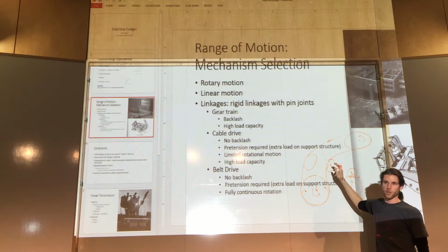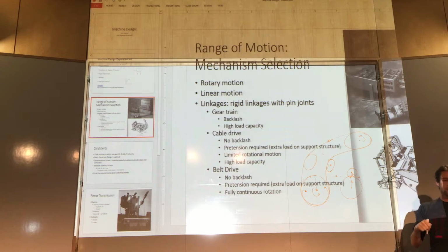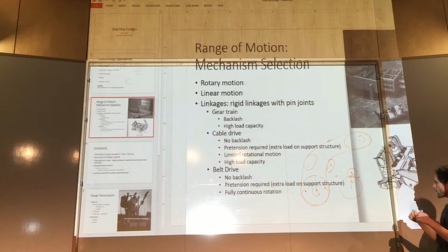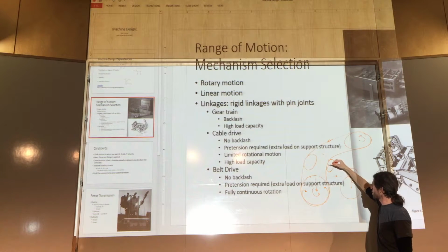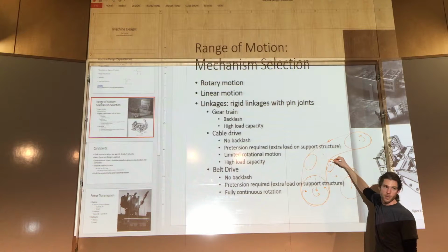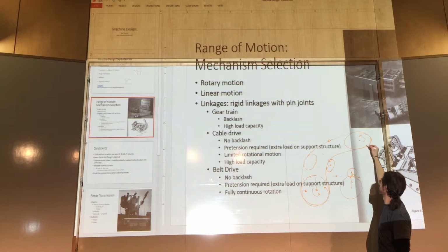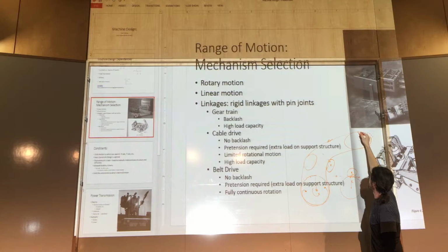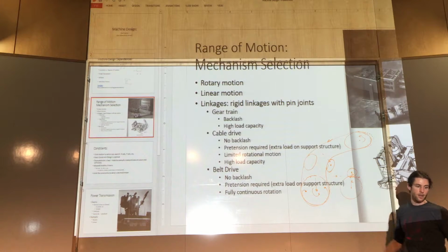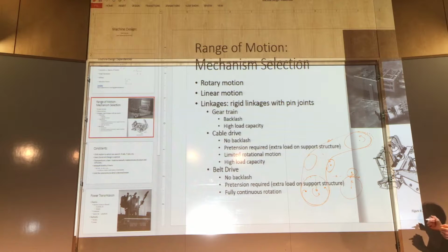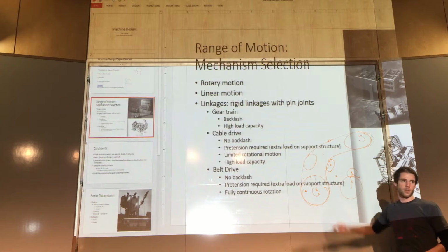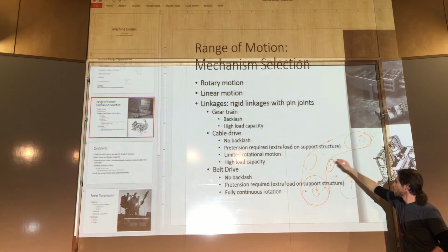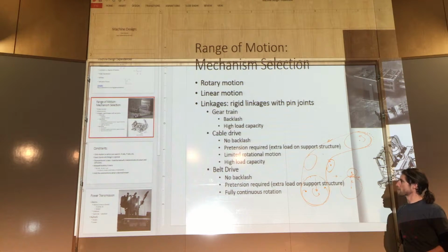Cables don't really like to be pushed, right? You can picture that if you're not careful, you can actually cause it to pop off of this pulley that's right in here, or even off of this pulley, because you can end up having it bunching up all the way to that last little bit of contact area there. And so you have to pre-tension the system, and you have to pre-tension it to about 60% of your total working load. So basically a little bit over half of what it's going to be, because that's about how much it's going to detension on the opposite side.